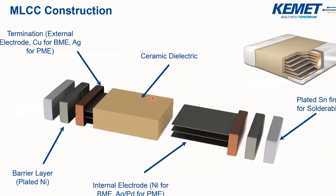Now this shows an exploded view of an MLCC. You can see the ceramic dielectric material along with the internal electrodes. MLCCs are made using either PME, precious metal electrodes, or BME, base metal electrodes. Now historically, MLCCs were made from PME materials in which their electrodes were made from precious metals such as silver and palladium. Now over time, as dielectrics became thinner and cost needed to be reduced, suppliers switched over to BME materials in which the electrodes are made with either nickel or copper. Now today, the overwhelming majority of MLCCs use base metal electrodes such as nickel.